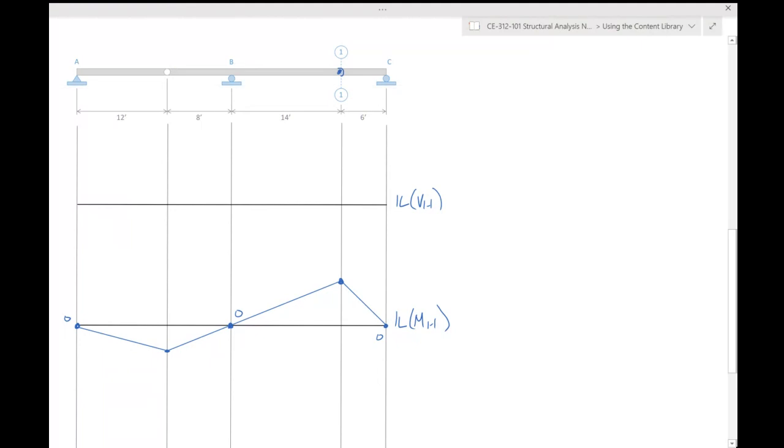Now I'll talk about doing the values. How do I get the values? How do I get this value right there? Well, the height is to 14 plus the height is to 6. That's the total slope. That has to equal 1. Simple. All right. Once I've got that, use linear interpolation, use slope ratio, get that. So I'll go ahead and give you some answers on that. X is to 14 plus X is to 6 equals 1. This comes out to be H is 4.2. So that is 4.2.